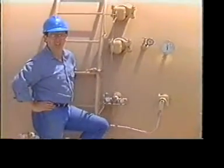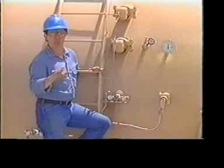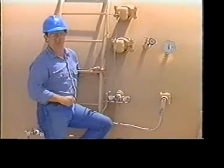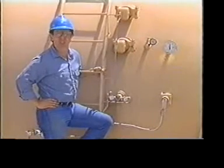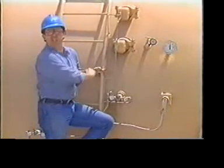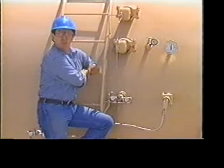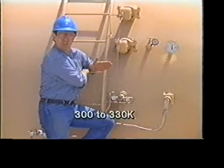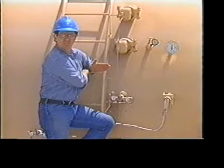Operating temperatures are also an important part of the treater operation. The lowest possible temperature to adequately treat the emulsion should be used. The electrostatic treater has an advantage over conventional heater treaters because lower temperatures can be used. Treating temperatures usually range between 85 degrees Fahrenheit and 135 degrees Fahrenheit.